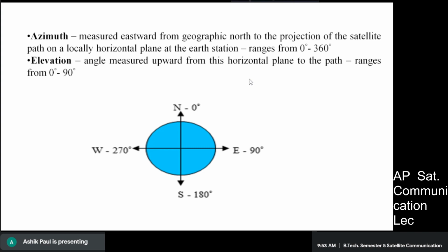No, actually, you see, it could be in any of these two quadrants. Theoretically speaking, the geostationary satellites could have azimuth ranging from 90 degrees through 180 to 270 degrees, because your Earth station is at the center. So looking south, you have both these quadrants where you can expect to find the geostationary satellites. Those will be the two quadrants.